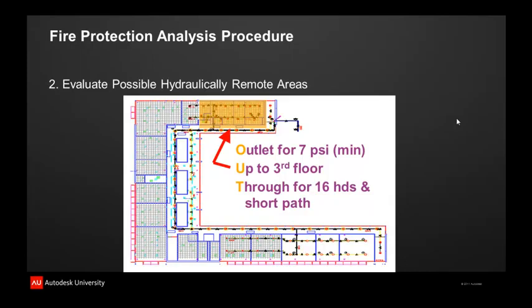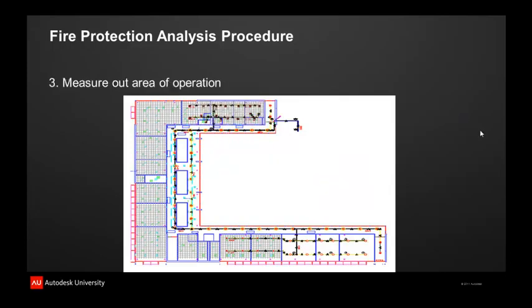In fact, all other things being equal, 16 heads would have almost 4 times as much friction loss as 8 heads. It may be that the path is about 4 times longer, and that might even them out. Still, each area should be considered in terms of these 3 ingredients to the total pressure required, what it takes to get out, up, and through. For the remainder of the example here, we're going to focus on that first area. Ultimately, both would have to be done and compared.